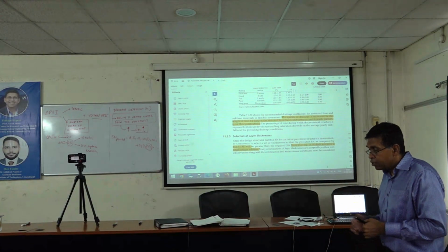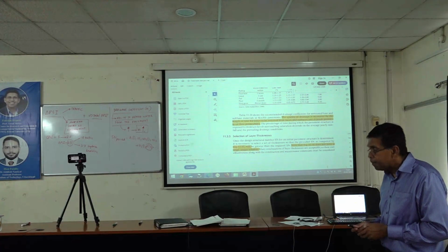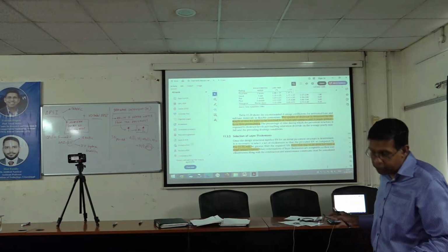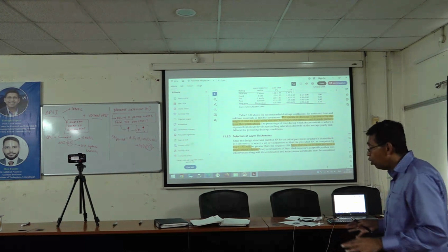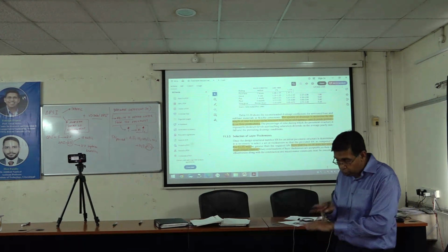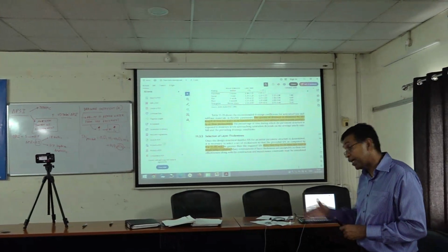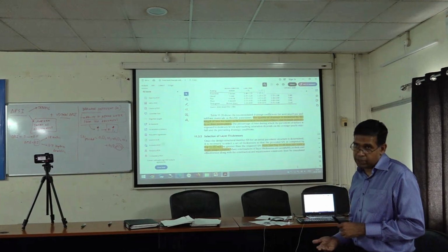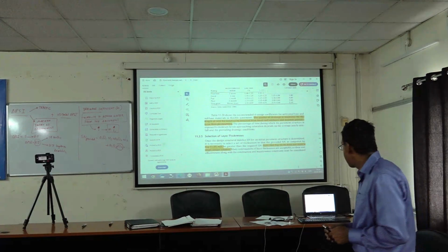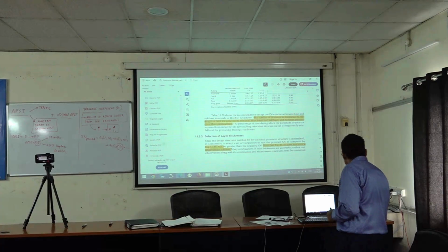So you will have water entering from different sides. You see what I'm saying? You will have water entering from the edges, from other parts of the pavement, and you just want to build a layer that will allow the water to go through. But you don't want the water to go through from the top. You want a cross slope to get the water out from the sides. But then water could enter from the sides into the lower layers, and that could be a problem.